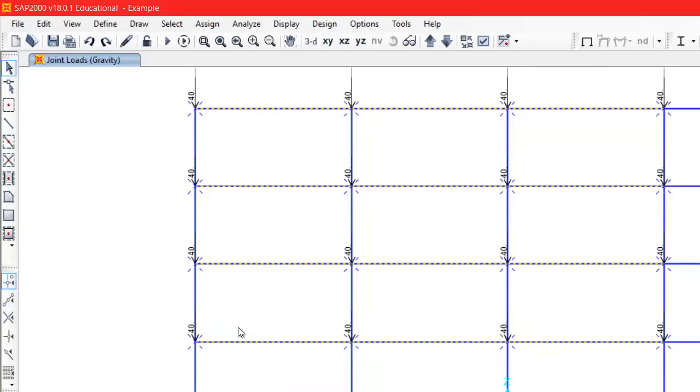The mass, how do you calculate the mass? Again, if I look at the plan view, you have system here, system here. I'm looking in this direction. I have the loads acting, because I'm modeling this one. So I have the loads here. All the loads, tributary, everything, and P delta. And then if you take the load, how do you transform it into mass? How do you transform force to mass?